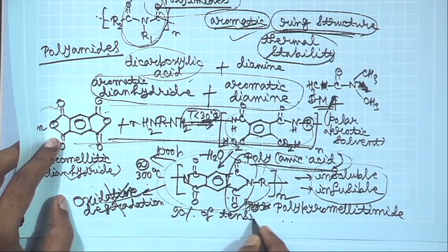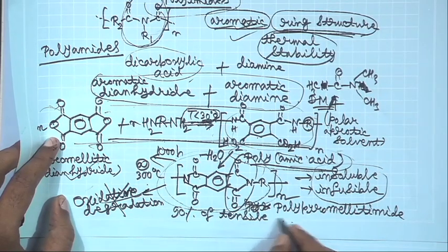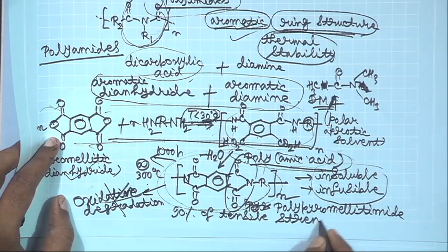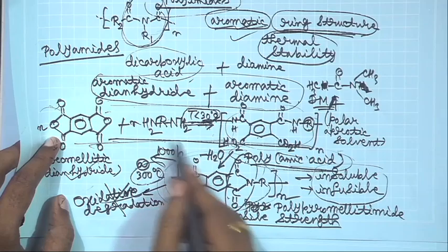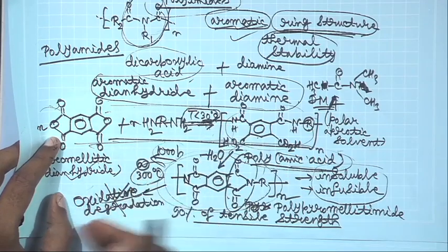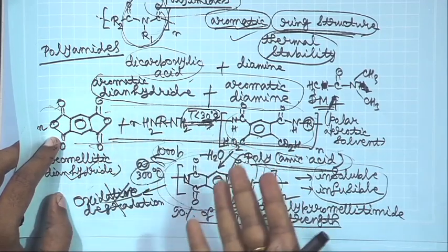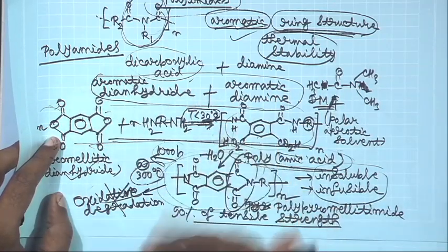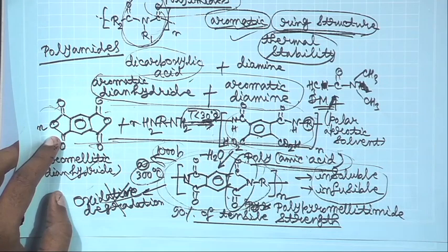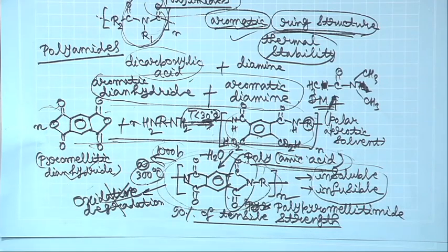So, you see that it has exceptional thermal stability, and mechanical property is not degraded even at high temperature for a long time. Not only that, oxidative degradation does not occur, even though you are exposing it to air at high temperature. Many reactions will be accelerated at high temperature and polymers might degrade, but not polyimides. That is the reason why these are specialty polymers.